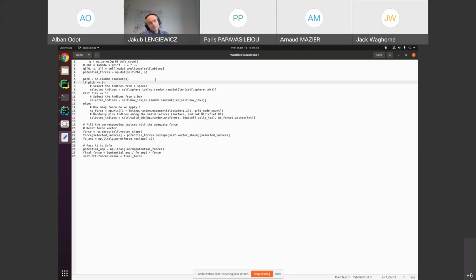Okay. And did you try to use more or fewer modes, to see if there was a big change between 2 modes or 5, 10? Yes, the first 3 modes provide very good deformation because it's usually what you intuitively think the object can do. For example, for the beam, it will be vertical bending, lateral bending, and twisting. If you go to the 4th, 5th, 6th, etc., you will start to have this kind of double bending where it's bending to the left at the base of the beam and to the right at the tip.